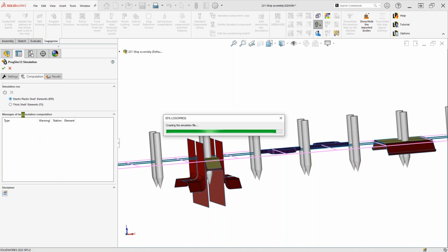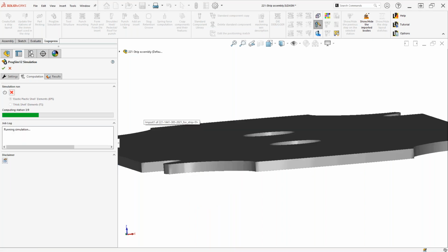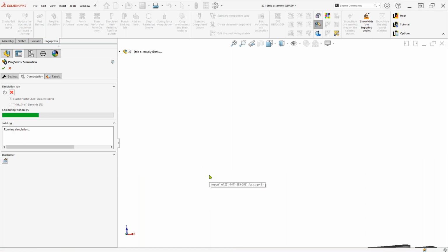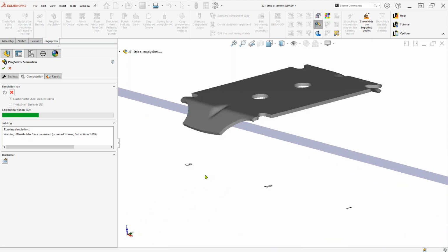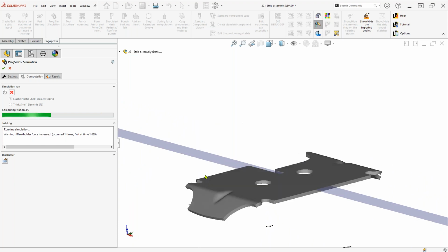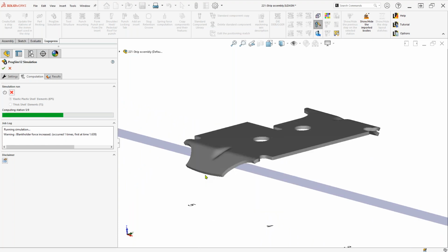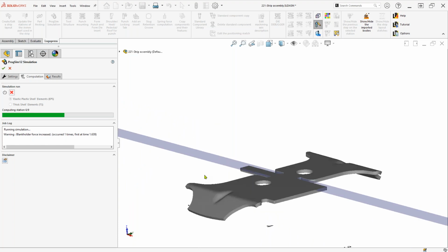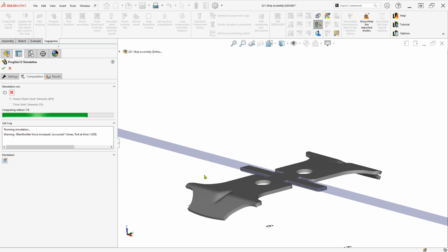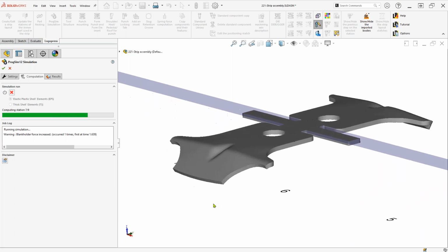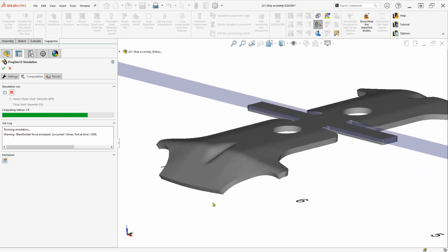And this is basically taking all of the surfaces that we selected and all of the parameters that we fed them and exporting that all out to the AutoForm incremental solver. This is the same solver that runs in the higher end software, but with various limitations that are applied to Proxim here. So it's running the same simulation, but it's helping you extract that from SolidWorks here and feed it into the AutoForm solver.